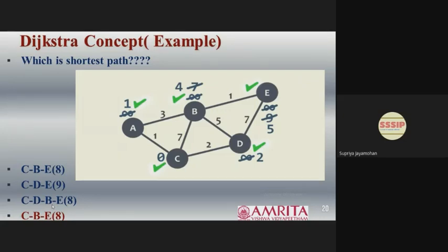You could see that in the video. As we were seeing the robot move, it doesn't move so smoothly. It has a certain lag as it moves. So that lag is what we would have at each node or at each position. So perhaps in addition to the distance, we should also keep minimum nodes visited as another criterion, which is actually not an original part of Dijkstra.